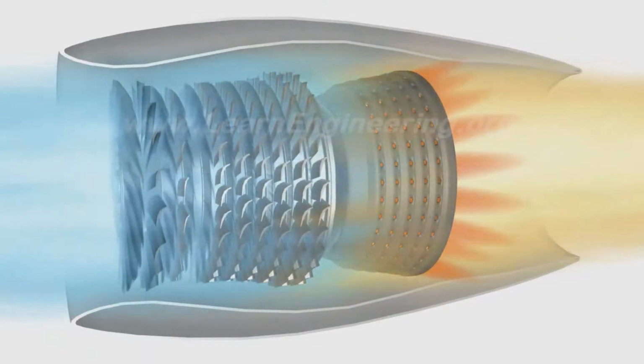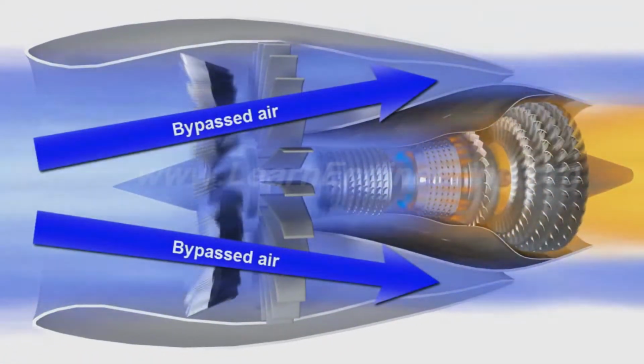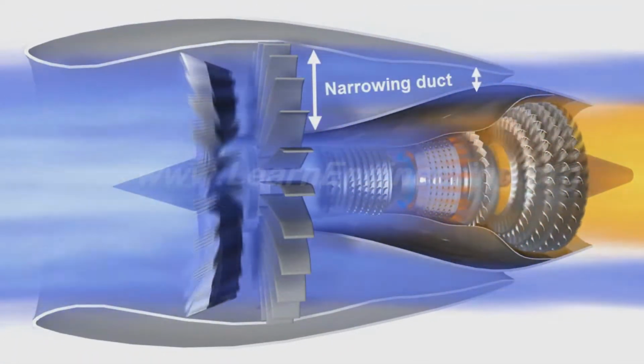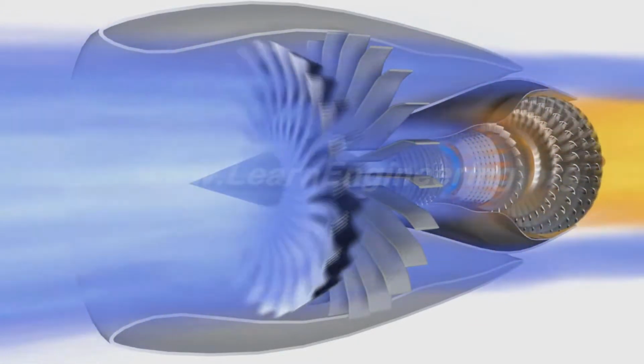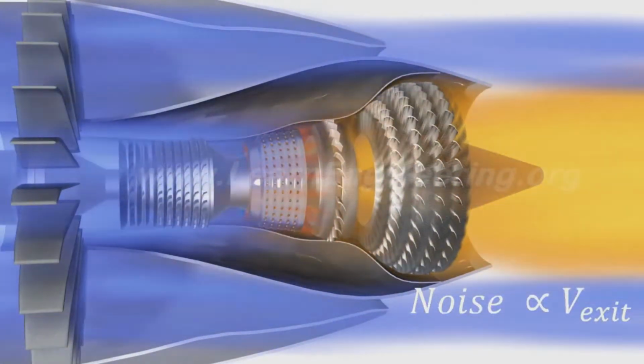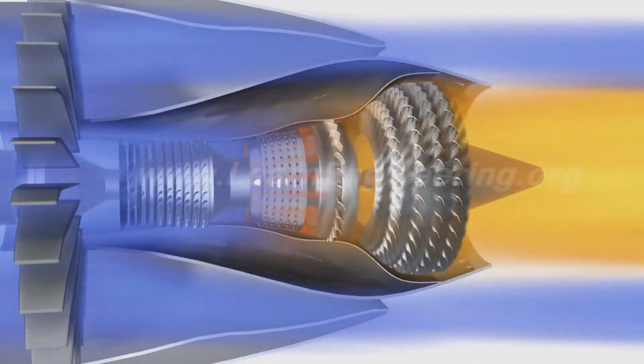Turbojets have been replaced in slower aircraft by turboprops because they have better range-specific fuel consumption. At medium speeds, where the propeller is no longer efficient, turboprops have been replaced by turbofans. The turbofan is quieter and has better range-specific fuel consumption than the turbojet. Turbojets are still common in medium-range cruise missiles due to their high exhaust speed, small frontal area, and relative simplicity.